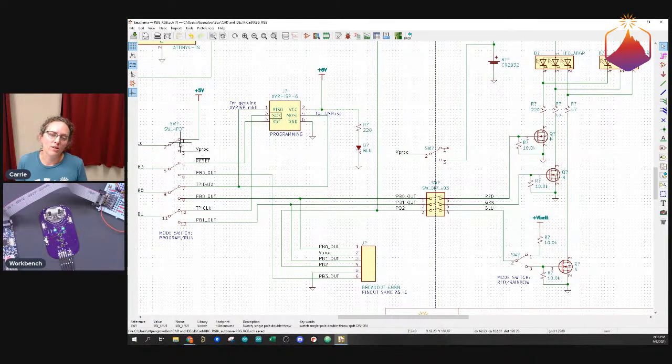Yeah, so this does not disconnect the battery if they're jumpered, right? Because basically the only way of getting 5 volts into the board for a programmer is through this connector right here. So it has to come in here and then be jumpered here, so it's on the opposite side of that switch. So that switch would not prevent that from happening.